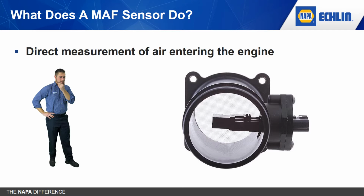There is a direct correlation to the amount of current needed to maintain the element's temperature to the mass of air that flows past the element. This eliminates the need for air temperature or pressure sensors in the calculation of mass. Often, these sensors have an internal IAT sensor, but that is not used for the calculation of mass.